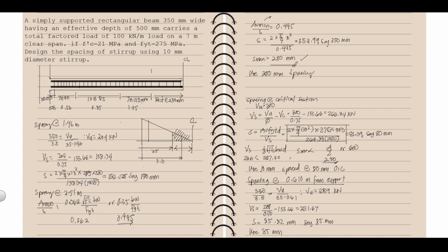So yun lang class. This is how to design our beam in shear. Okay, so of course, this is the left portion. Like I say, this is symmetric beam. So, kung ano yung itsura dito sa left, dun sa right. So, this is one of your requirement. So, sana makakita ko ng ganitong drawing, no? Sa requirement nyo, no? Yung spacing of your stirrups.